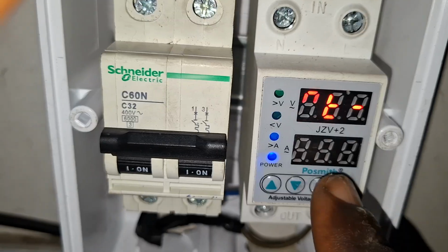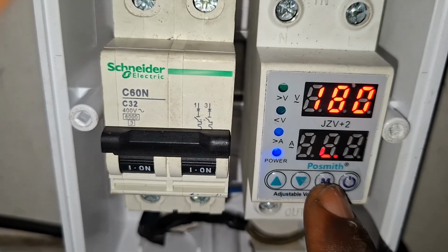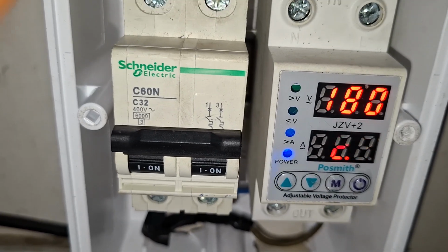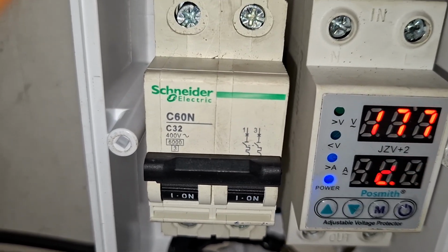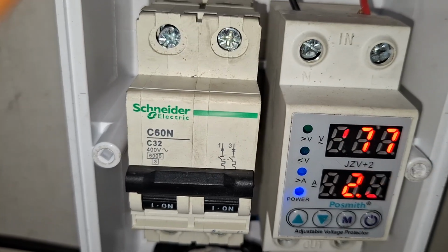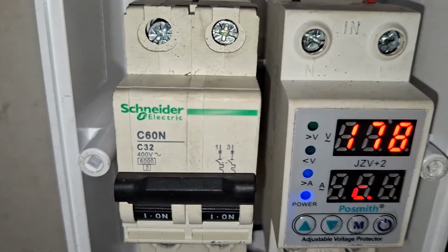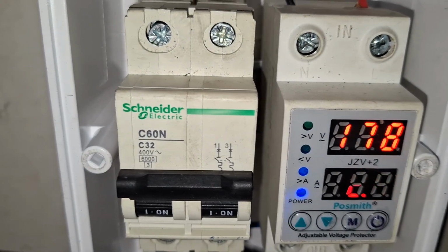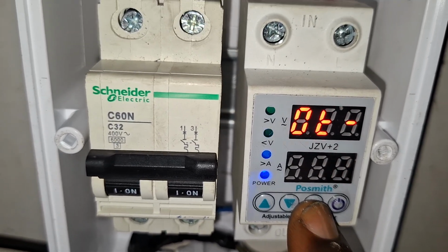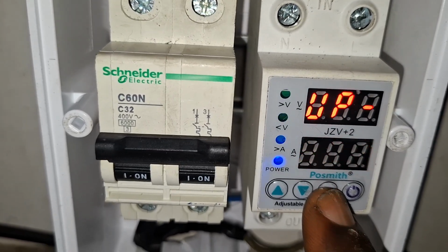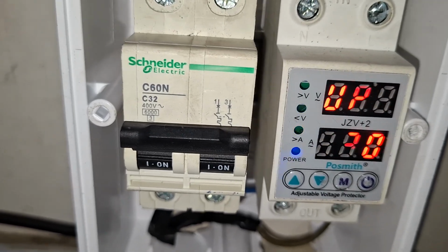Now after the delay seconds the AVP will come on. Let's go further to make sure we set it up. The first thing we are going to set is the over voltage protection. What is the value of voltage you want to give your inverter in case there is a surge or the voltage is high? You want to make sure that the inverter will not blow up or get damaged. So we have to set the voltage. Remember, when you press the mode first, it gives you your time delay, and the second one is over voltage protection. My over voltage protection here is 230, which is also our advice, the maximum you can set.